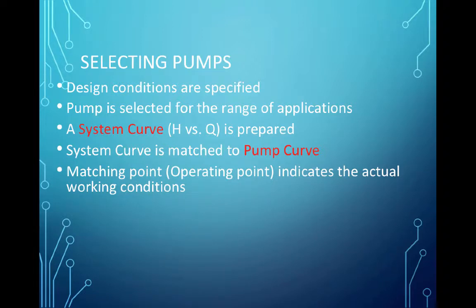Okay, last part is selecting pumps. So we need to know about how pumps perform, because we're going to put them into hydraulic systems, and we're trying to match pump performance to the needs of the system. So we usually specify the design conditions, and then we select a pump for the range of applications.